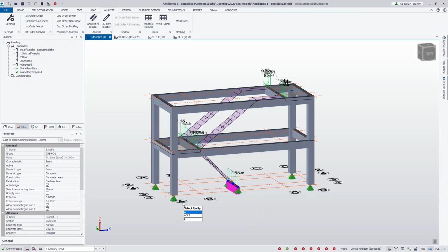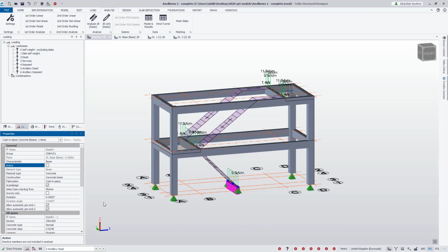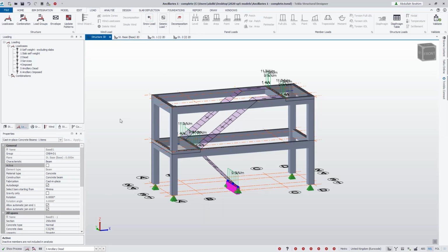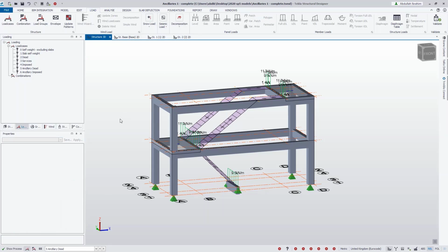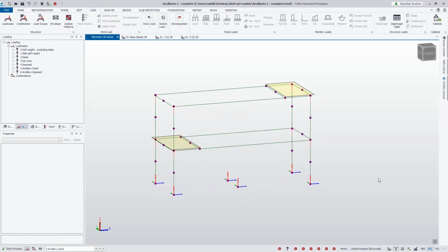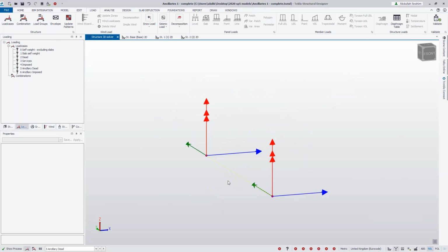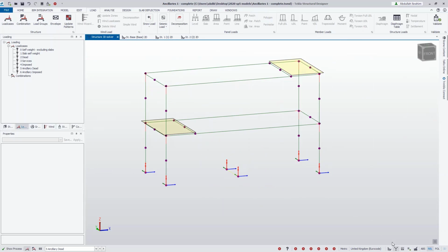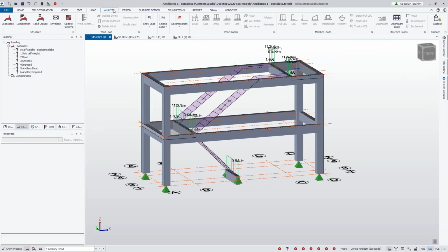If we click over here and make this member inactive and perform the decomposition again, we can see that the decomposition is the same. So it's still decomposing onto this member, which, if I were to just look at the solver model that we're currently working to, we can see that that member there does exist. However, it's modeled using a dotted line in the solver model, meaning that that member is no longer active.